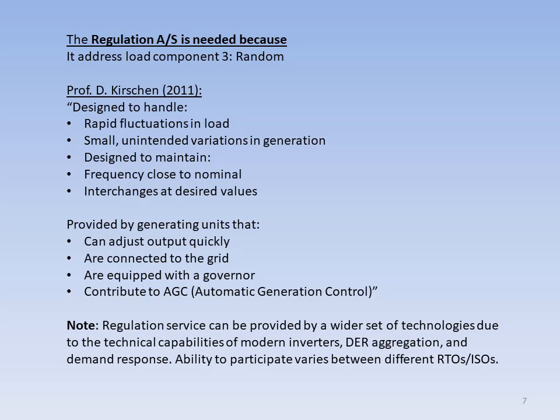Technologies and market rules are evolving. It is the stated goal of CAL-ISO, other grid operators, and the FERC to enable participation of these newer resources in organized wholesale electricity markets. To reiterate, regulation's mission is to compensate for fluctuations and supply and demand randomness, thus maintaining frequency near 60 Hz and a balancing authority's interties at desired values.